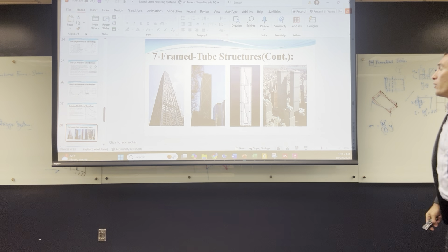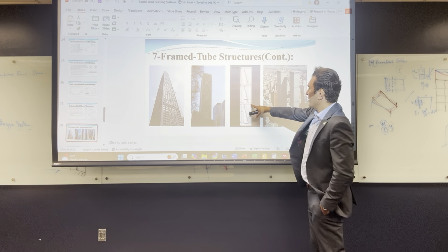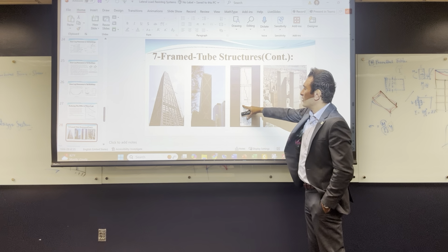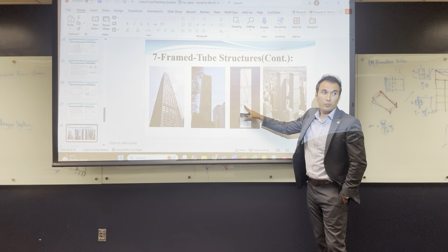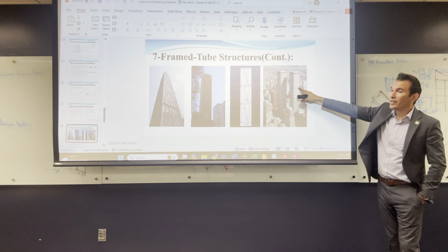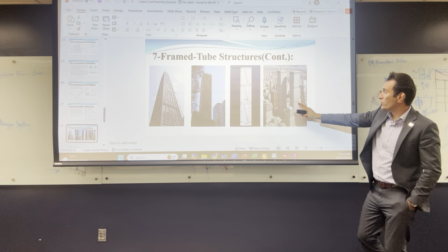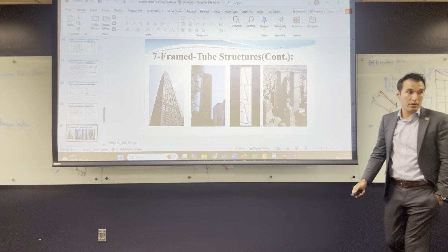So that's also one way to do it. And if you look at this building here, you will find that there's a solid concrete section, which means that it has outriggers. Like here, can you see this area? It's not the same, which means there's a solid section here, so there's an outrigger here, an outrigger here, an outrigger there, right?